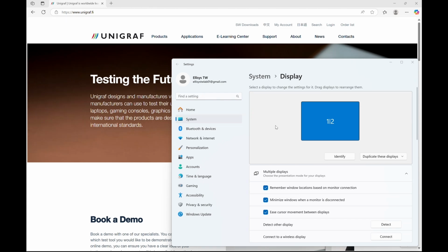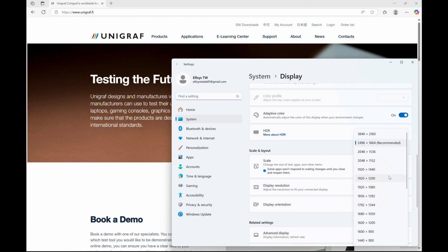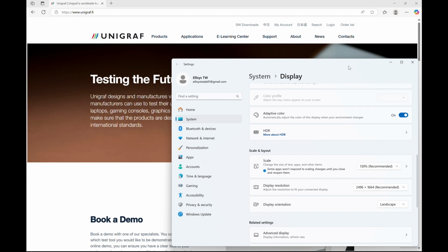Now let's take a look at what resolutions this DP source and DP Sync connection can support. As you can see here, it ranges from 4K all the way down to 800 by 600. When we test this DP source, the laptop, we can choose to test every supported resolution or only select a few for automated testing. This is where the UTC 274 comes in. By working with a Python script, we can perform automated DP testing. Next, we'll demonstrate how this works.